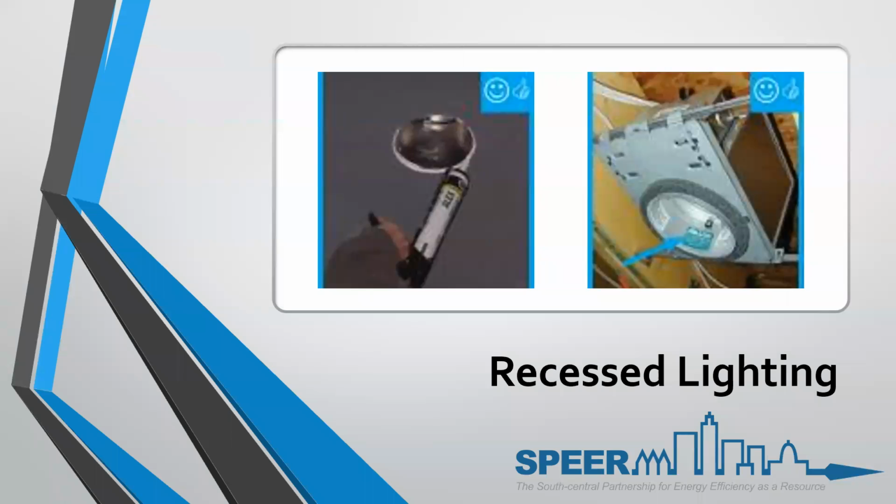If it's installed without a gasket, it should be caulked to the sheetrock or ceiling covering or air barrier around the light. And now manufacturers usually install the gaskets at manufacturer levels. And so when you open the box, the can already has a gasket on it. Most of the time, it doesn't have to be installed by the electrician. If it has to be installed by the electrician, usually they just throw them away. And when they throw them away, they need to be air sealed with caulking.